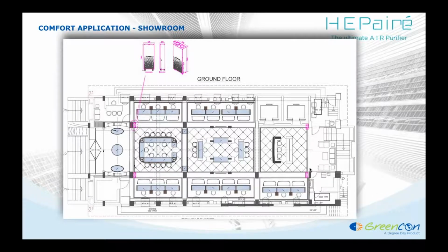Actually, in another case we are also discussing that, if you see on the right hand corner, this is the AHU room, and the unit can slide inside the AHU room where the return air is getting flooded. You can also utilize a ducted port to connect it to your existing fresh air and recirculating air conditioning duct supply so that it gets uniformly distributed and the filtration happens in a flooded way.